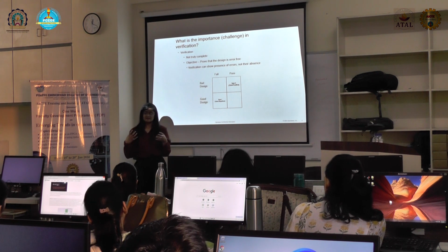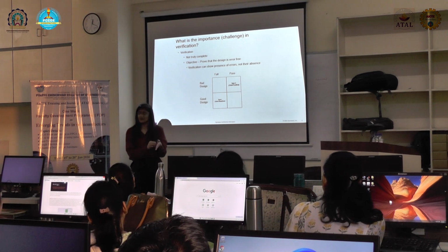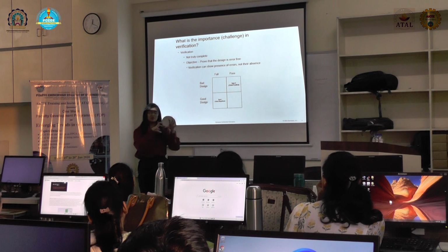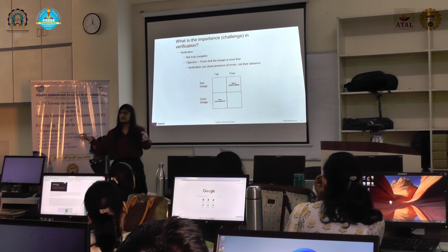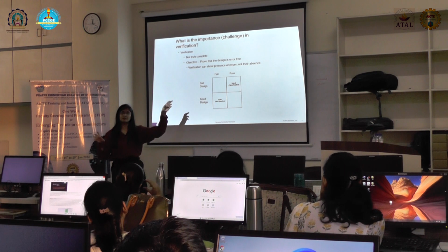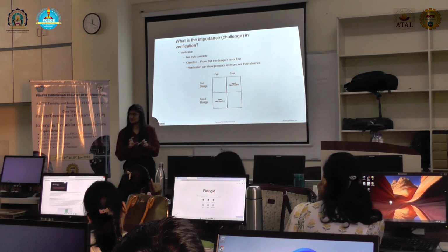Now, in some scenarios we are not running that specific scenario. We have cover points and cover groups developed for it, but we are not running a test case to cover that particular coverage. In that case, we can say it's a false coverage. It's collecting a default value, which is not intended to be covered in the scenario coverage.